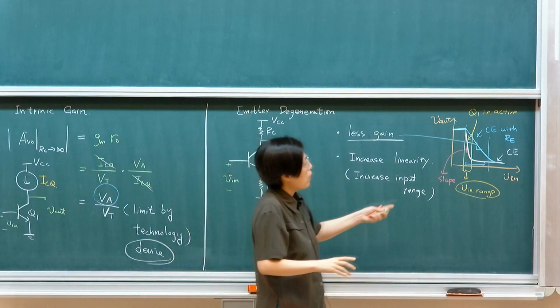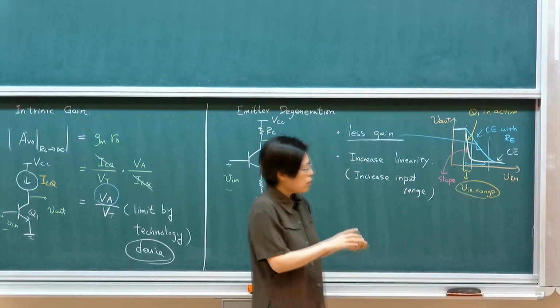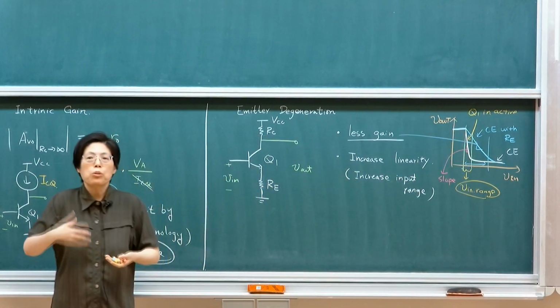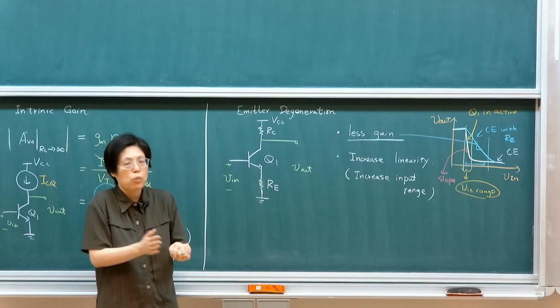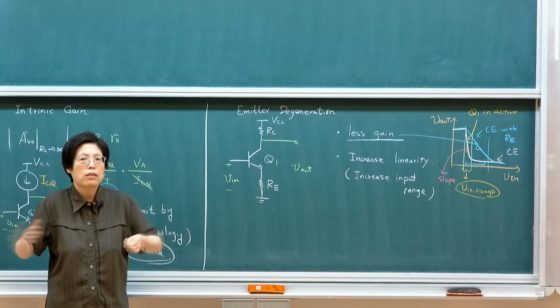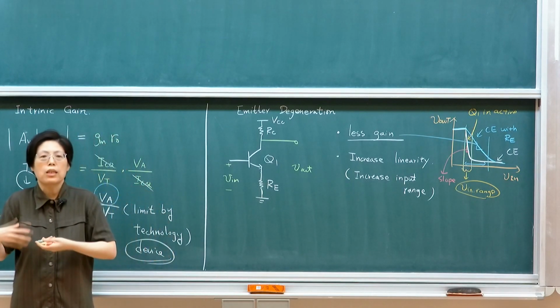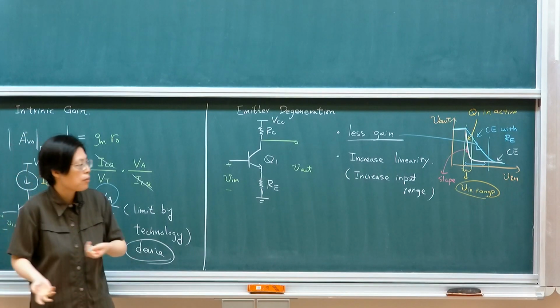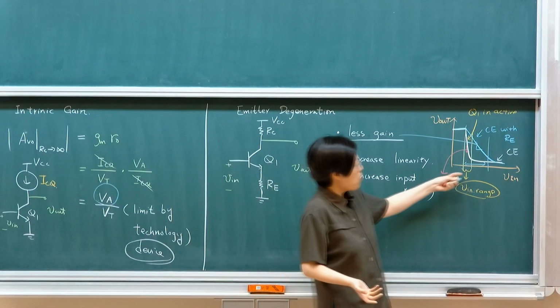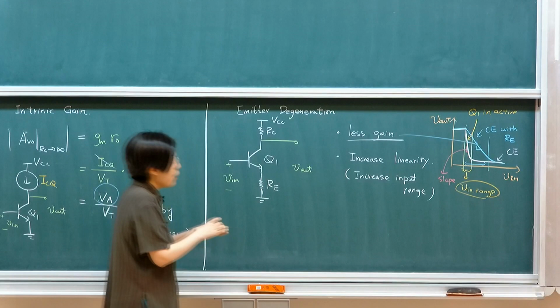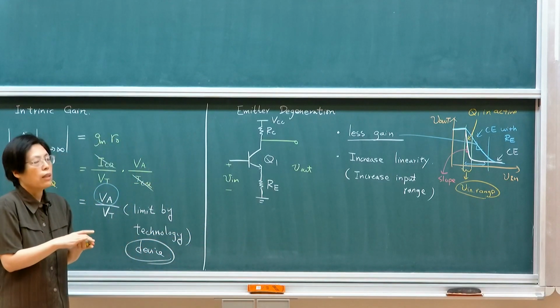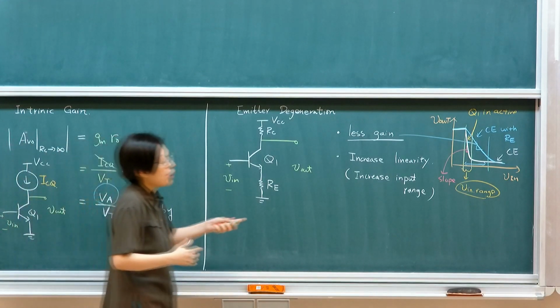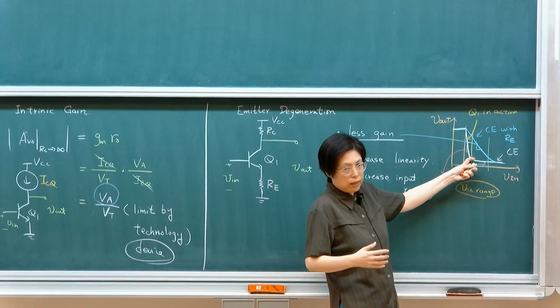And the other thing is that it will allow you to have what we typically refer to as linearity, or truthfully reflecting your signal, because you won't be hitting the boundaries that easily. Once you hit the boundary, meaning there's distortion in your signals, that's the thing we don't want. The reason why this is affordable is because initially the gain is very high.